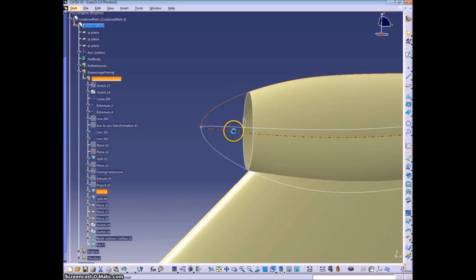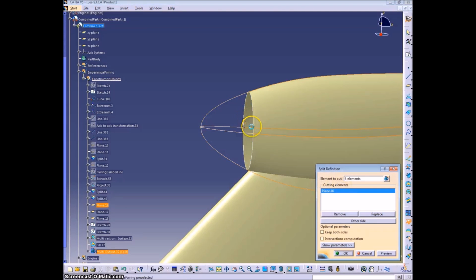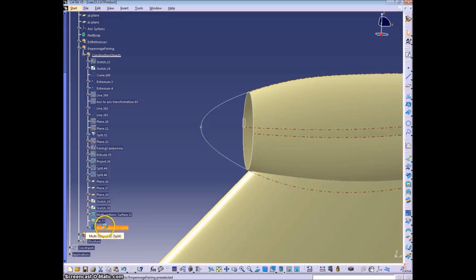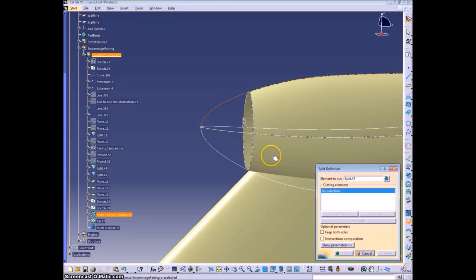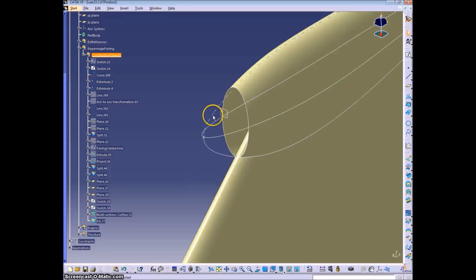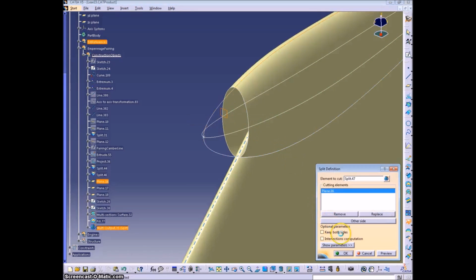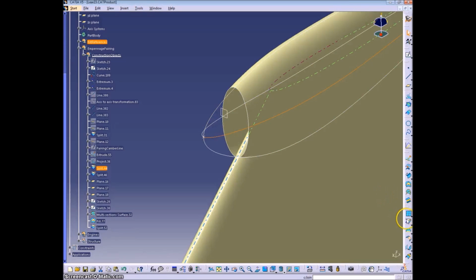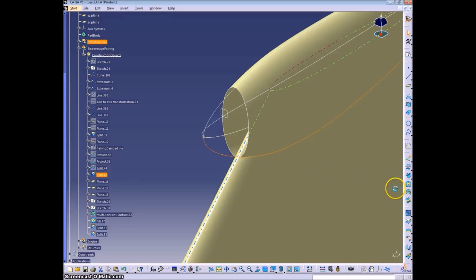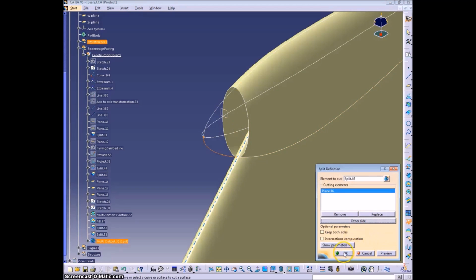In the front, we're going to do something similar to what we did with the nose cone. I'm going to split all of these curves so we just have this segment at the front. Have to do it one at a time. Once we have all those, we will fill in each section using the 3 curves that enclose a section, adding some tangency supports, as you'll see.